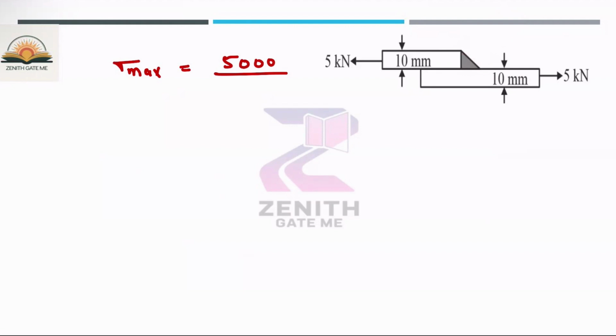So that means what will be the area? This is the throat thickness T, because this height, which is nothing but H, this is the throat thickness T. So what will be the area? This throat thickness and the length of this weld. This is the area, basically. So the throat thickness into the length of the weld, which you have to calculate.